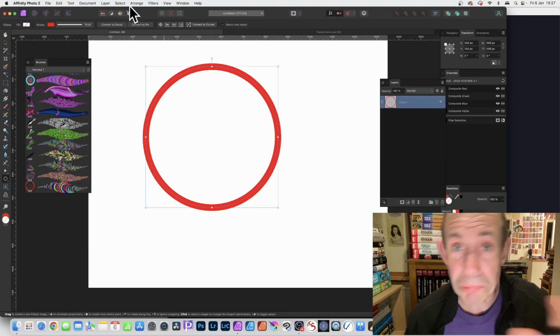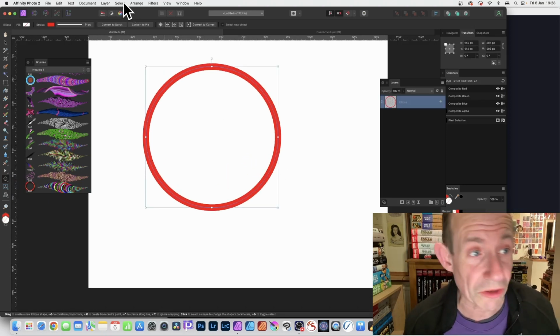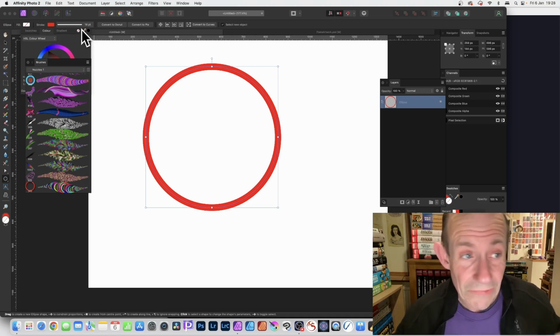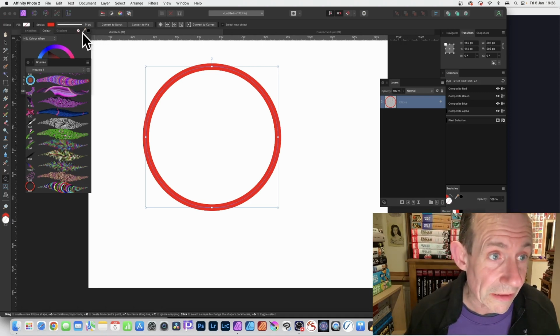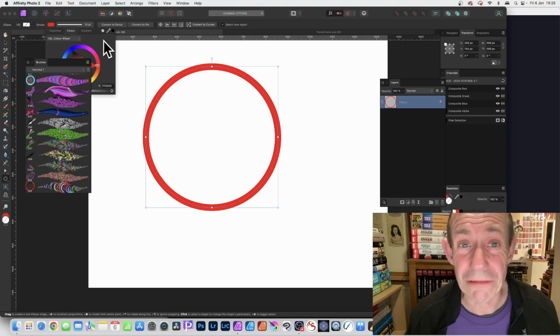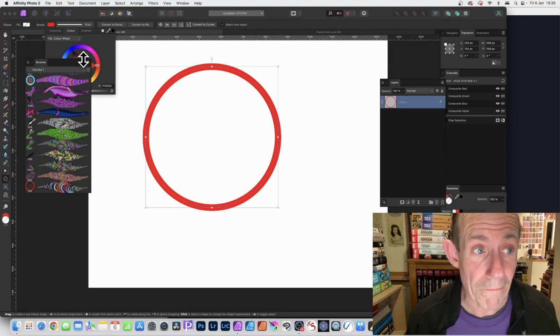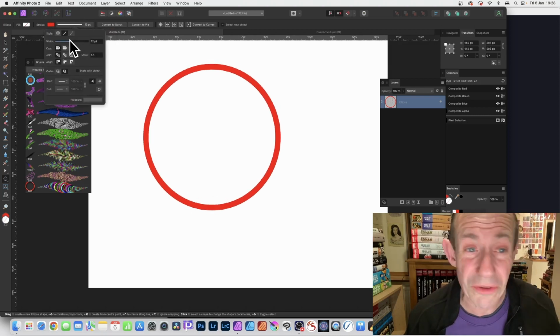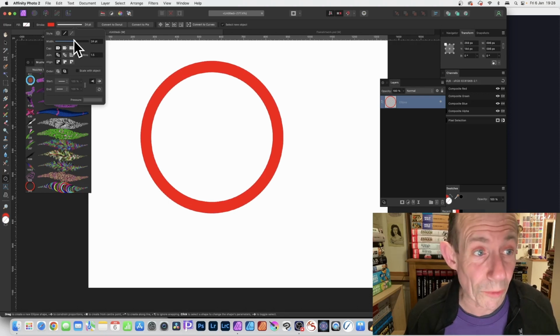And you will have probably a different setting for the fill and stroke. But what you need to do is go up here, top left, and just click here for the fill and make certain there's nothing there. So you just click here. Make certain that's clicked, and then the stroke, simply click and set it to red, green, whatever you want. But also set the size. Now I'm just going to go for 14, but of course you can vary it, 20, 24.